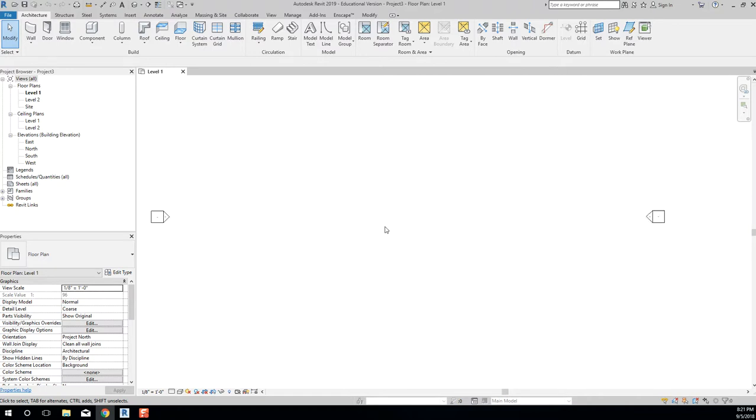I can pull it towards me and zoom out. I can double click the middle roller twice very quickly and zoom extents. I can also, just like in AutoCAD, hold the middle roller button down, move my mouse around, and I'm panning. So I'll leave the navigation at that for now, but you can zoom in, zoom out, and pan back and forth.